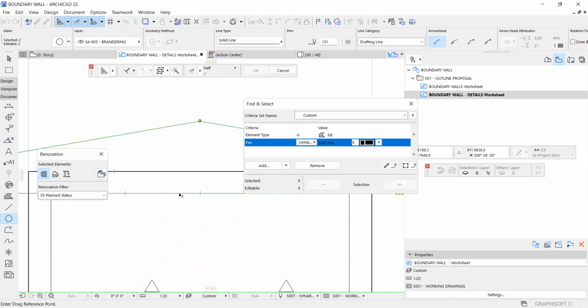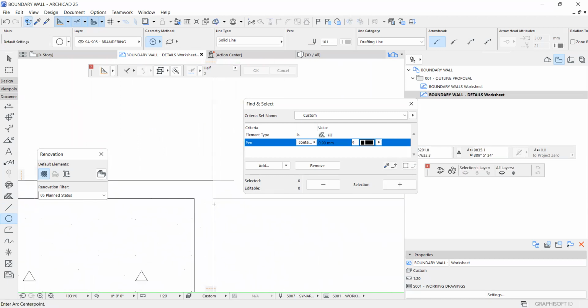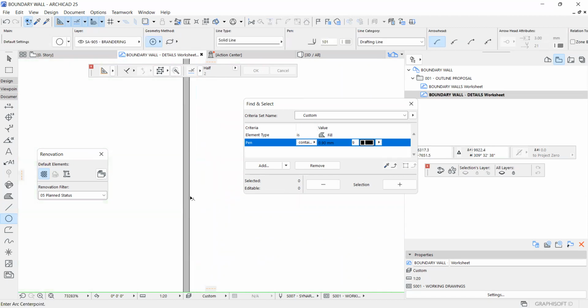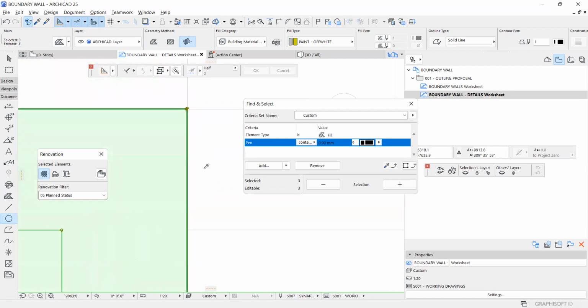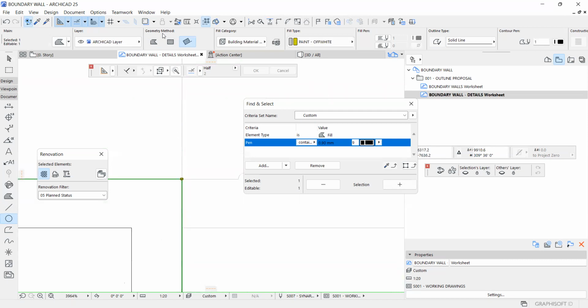And definitely we'll place it on top of the mortar, not on top of the paint. So it means that the paint will have to give way. Again, attention to detail. Your knowledge of construction will always come in handy. If you don't know these things, it becomes very difficult for you to handle some of them.